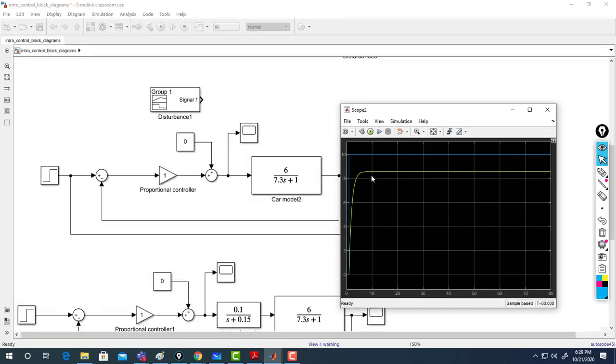So I just said one advantage of increasing the proportional gain will improve the steady state, so make the DC gain closer to 1 if you want, or you will decrease the steady state error. Let's try. That's what I said. But also the system becomes faster.